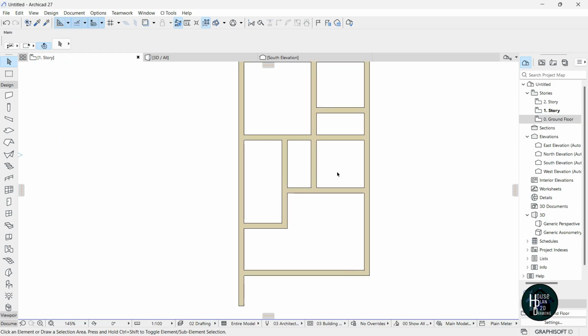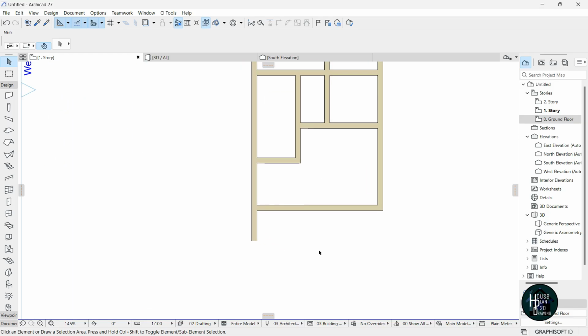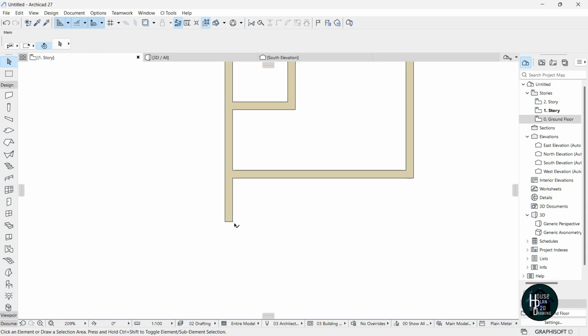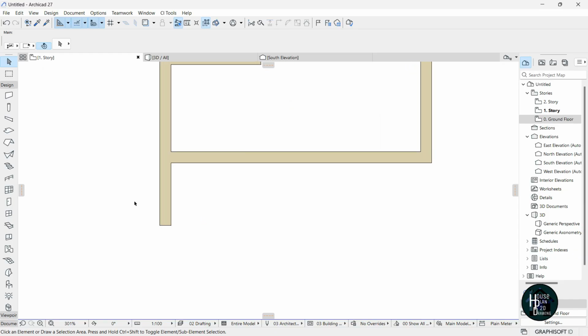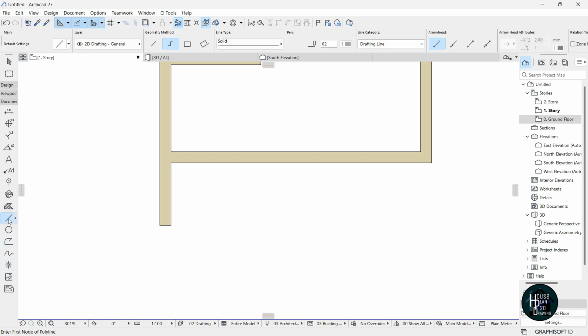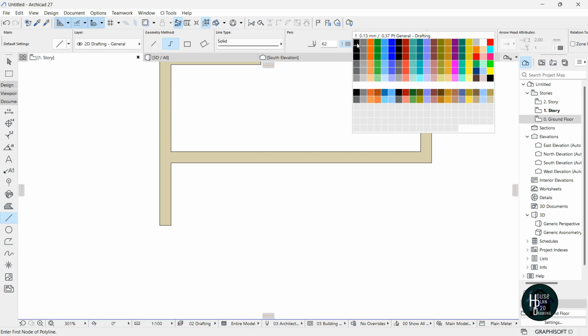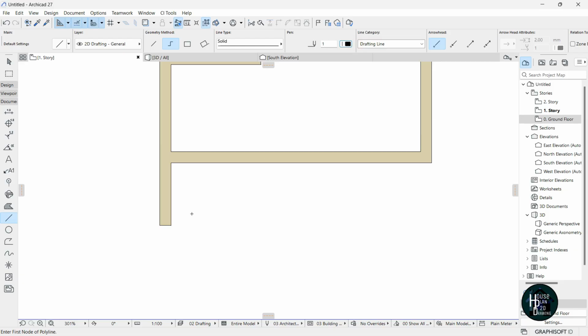But before we go about with that, I want us to come and quickly make a little adjustment to the drawing. For this side there's going to be a veranda here, so I'm just going to quickly make the area for it. I'm going to come to the document section here, click on it and come to the line tool. Click on the line tool, come to this side here and change the color of the line tool. Click this and I select this dark color. Now I want to just click this edge here, stretch it like this and give a distance of 4381.